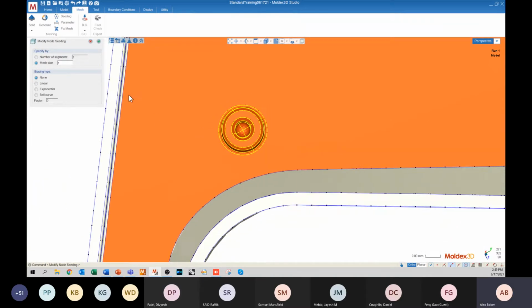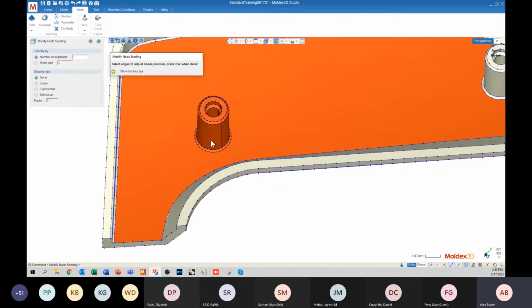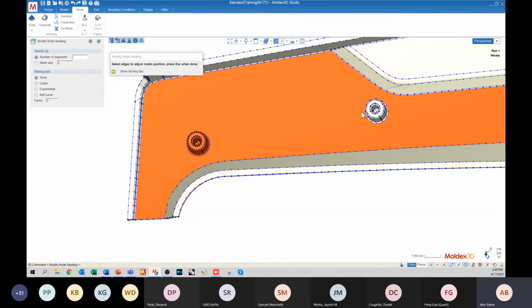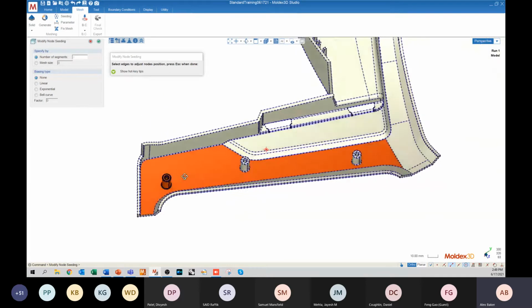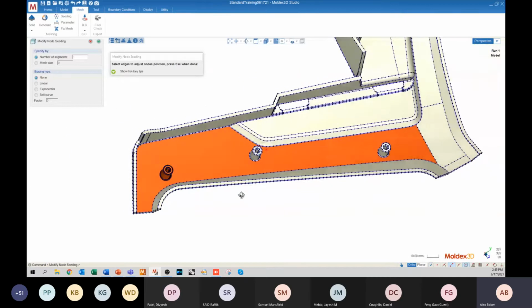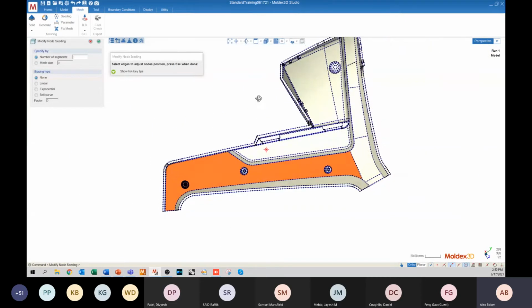All right, so once we set the mesh size to 1, you can go ahead and press enter. And then if you left click off in space, you can really see the difference between the new node seeding on this boss versus the old node seeding, if you contrast that to one of the other bosses. Now feel free to apply this setting to the other bosses as well. I'm going to keep the seeding as it is right now, just to contrast these two when the surface mesh actually gets generated.